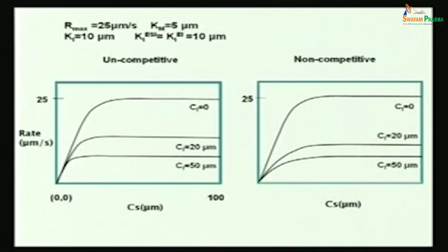So even if you are taking it out at a constant rate, say in a CSTR, what is the problem? The problem is the product gets to spend a fair amount of time in the reactor, right? As a result, it will still be inhibited. So yes, taking the product out continuously is a theoretically correct answer, but it's not a practically correct answer, because if you're using a CSTR, it has a certain residence time and you cannot do anything beyond it, right?